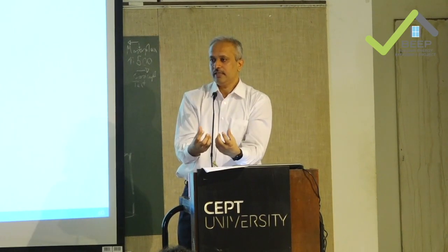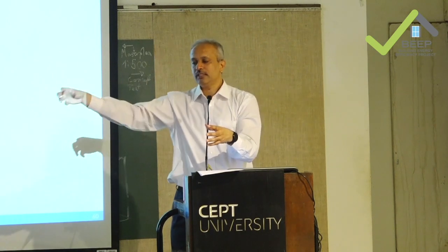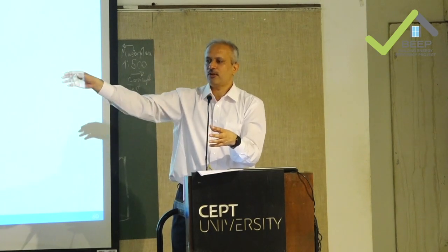Okay. Bhopal's buildings keep absorbing heat. So let's say it absorbs 100%, it rejects 95%. So 5% remains with them. Next day again 100%, 95% goes back. So cumulatively, it keeps everything, the entire mass is a warm mass. And that's what we call a heat island. Okay. So if you are using an air conditioner in a farmland, that air conditioner has to cool from 40 degrees to 27 degrees. Here, it has to cool from 43 degrees to 27 degrees. So that has an impact on energy as well. Right?